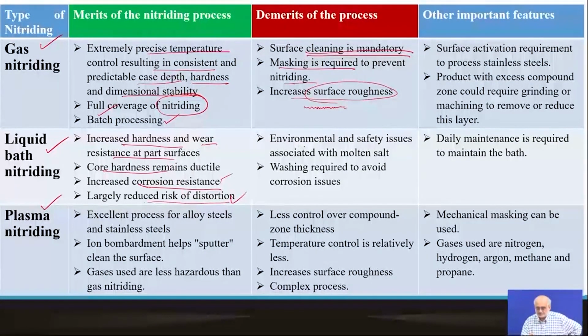The disadvantages or demerits are the following. First and foremost, you're talking about a huge environmental and safety risk. You're dealing with cyanide and such fumes, or a very high level of corrosion of the tank and so on, and you cannot shut down, you have to run it 24/7. So these are all disadvantages. And you also need quite a bit of washing or cleaning of the components, because if the salt still sticks to the surface, then it's going to continue to corrode the surface. So you have to take care of that and follow up with some washing.